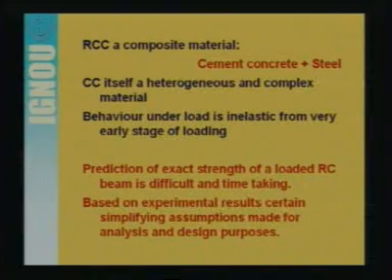Now, think about the material, reinforced cement concrete. It is a composite material composed of cement concrete and steel. The two materials in RCC are cement concrete and steel. Cement concrete, as you know, is itself a heterogeneous and complex material, because it is not made of a single material. Here we use aggregate, cement and water. So, the behavior of the cement concrete under load cannot be easily predicted exactly, because it is a heterogeneous material and its nature under load is complex.